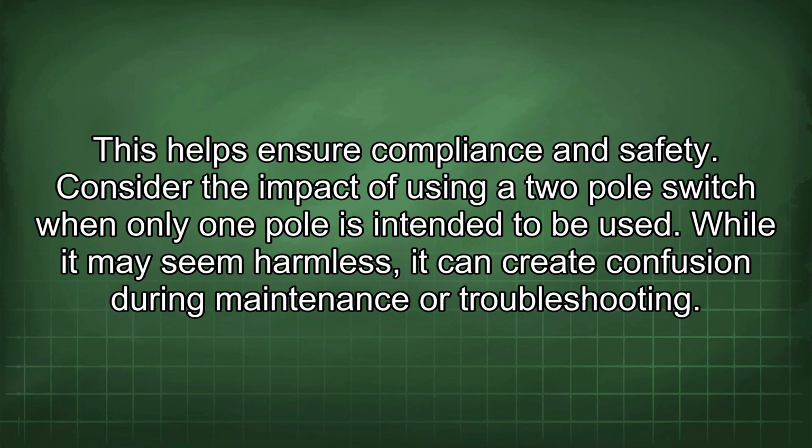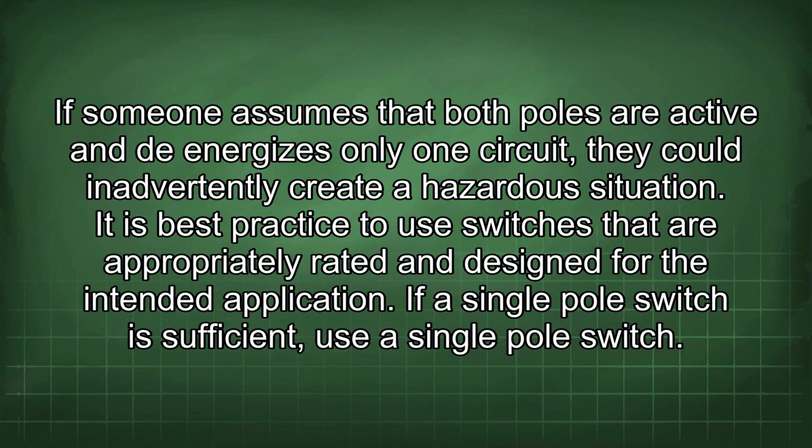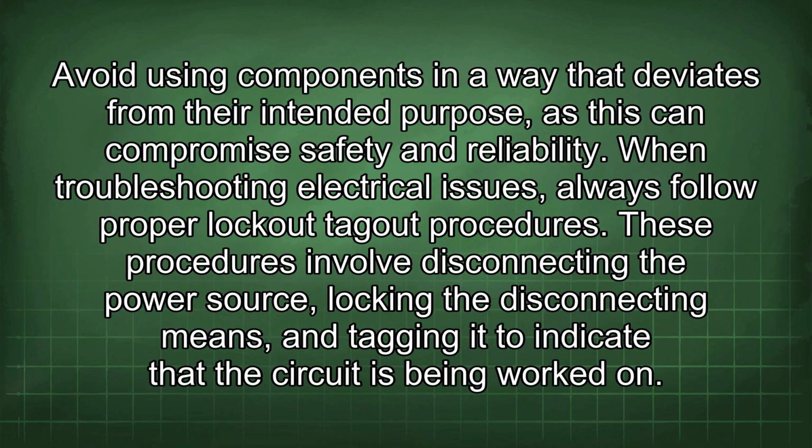Consider the impact of using a 2-pole switch when only one pole is intended to be used. While it may seem harmless, it can create confusion during maintenance or troubleshooting. If someone assumes that both poles are active and energizes only one circuit, they could inadvertently create a hazardous situation. It is best practice to use switches that are appropriately rated and designed for the intended application. If a single-pole switch is sufficient, use a single-pole switch. Avoid using components in a way that deviates from their intended purpose, as this can compromise safety and reliability.